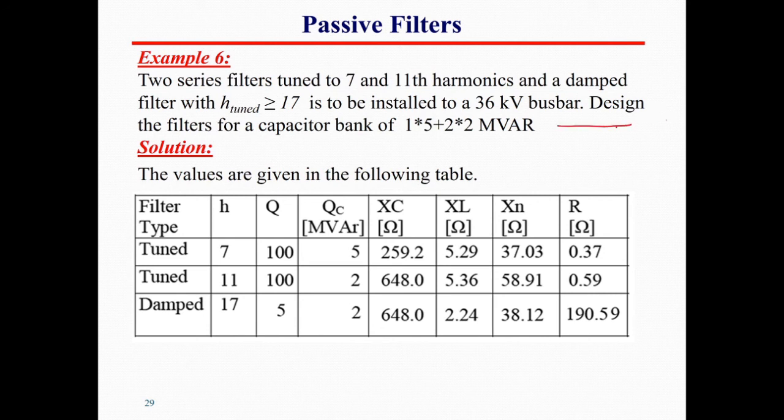So we have over here one single tuned filter, another single tuned filter, and then we have a damped filter, which consists of course of a capacitor, inductor and resistor. So we have those kinds of filters added to the system.